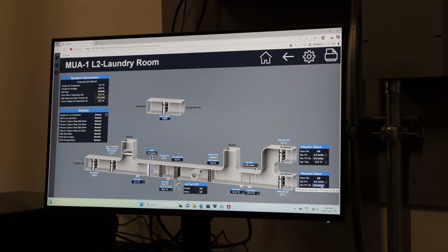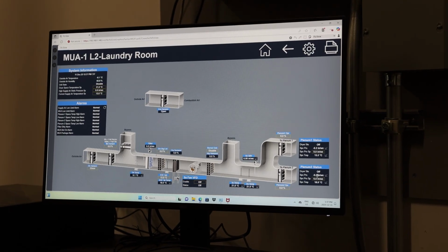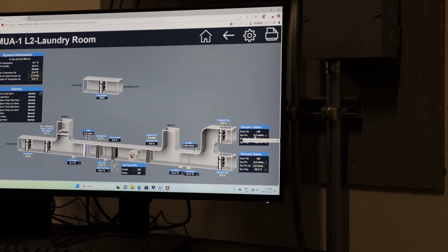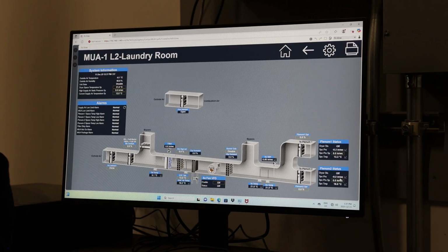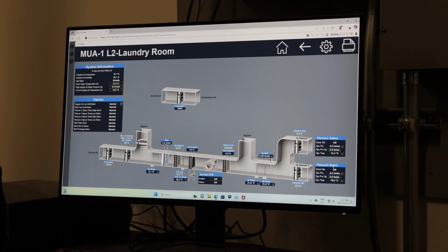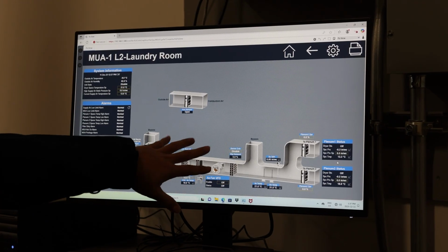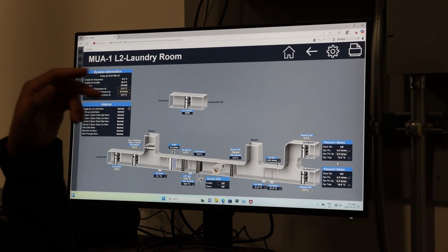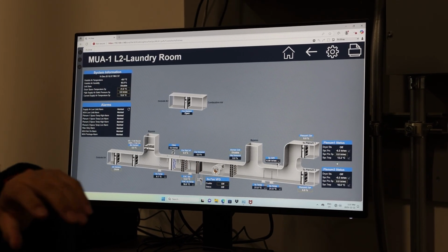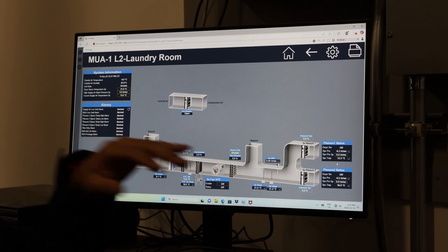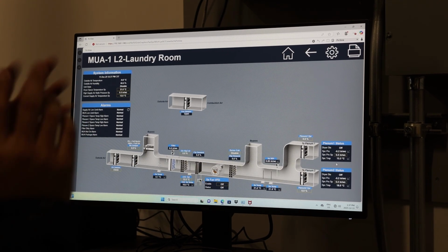Yeah. The set point space pressure, these are the space pressure. Right now they are slightly negative, and 2 space pressure, space temperature sensors. Maybe I will show you here. The space pressure. So the unit is actually maintaining the supply air temperature, right? But supply air temperature set point is being calculated based on the space pressure demand, space temperature demand.